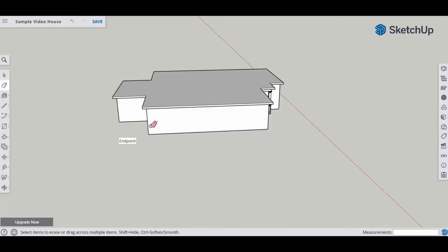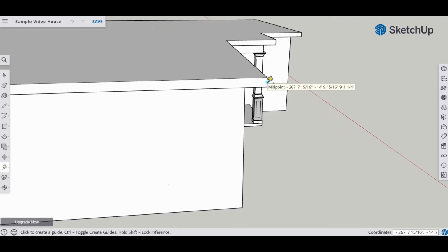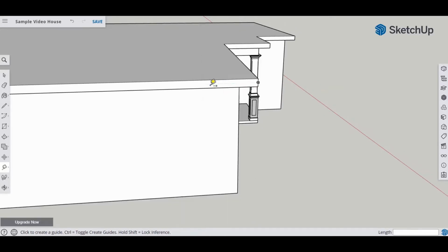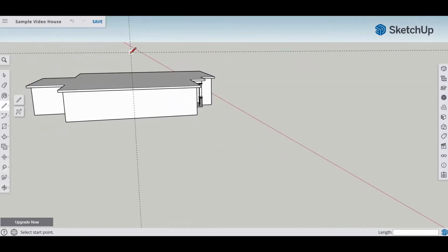I'm going to rotate this around. And so this distance is 37 feet. And I know that if you cut that in half, it's 18.5 feet. And I know that it's a 111-inch rise based on 18.5 feet. So what I'm going to do is put on a guide on here that's going to go straight up, make sure on the blue surface, and it's going to go up 111 inches, and then I know that half of this 37-foot side is going to be 18.5 feet, and so that's going to give us our middle point. What we want to do now is to actually create the roof.